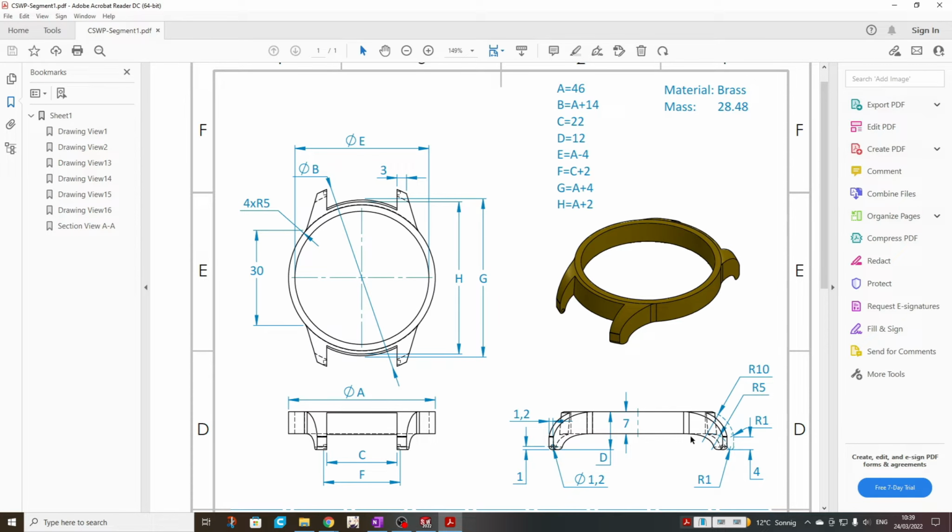Looking at this drawing, I can see that this is a straight cutout. It's easy, we can use the standard cut, but the cutout here is a bit more complex. There are two ways to do it: you can do it with a loft cut or with a swept cut. I will do it for this tutorial with a swept cut. But first we start building our base part, with this outer contour revolved around here, and then we go further.